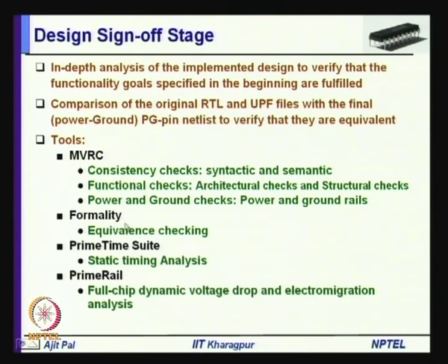Then you have got Formality, which does the equivalence checking, and PrimeTime Suite, which does static timing analysis, and PrimeRail, which does full chip dynamic voltage drop and electromigration analysis. So, with the help of this, the design sign off stage is performed.